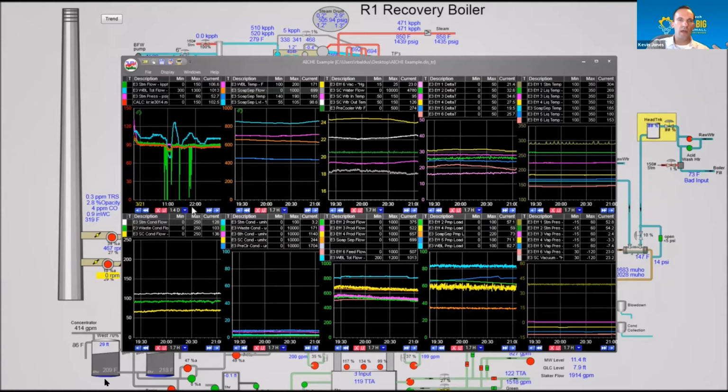So what he's going to do now is he's just going to hide that red tag so that it's not there. And so during normal operation, the operators can look at the actual steam flow. But if that's having an issue, they can just uncheck the red tag, and the virtual sensor will come into play. So it's a very simple example of a practical solution to a sensor having a problem. So in a matter of, again, a couple minutes, we built a virtual sensor to give real-time feedback to operations for a sensor that's having some problems. So again, another very self-service way of building, in this case, a digital twin as a sensor estimation for a virtual sensor.